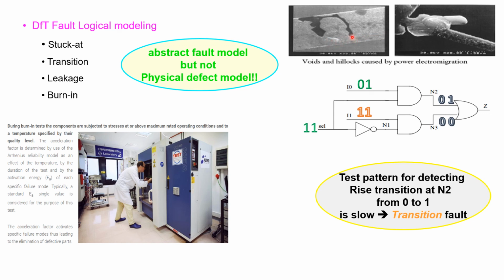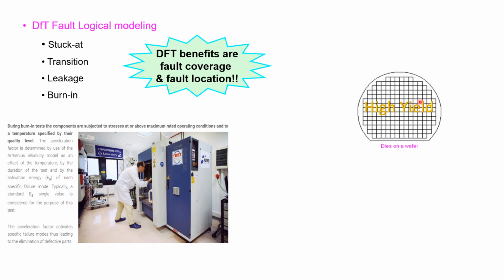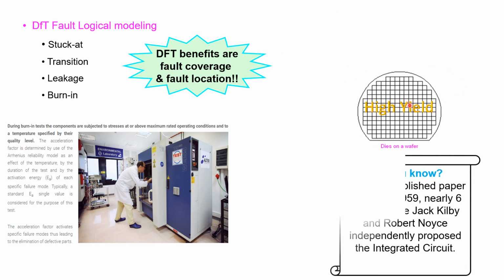Okay, a small width, I mean. So because of this, resistance has increased. Because of that, the rise transition will change, so the rise delay will also change. That should not happen. That we have to figure out in the silicon chip, and then we have to take out those offending chips. That is how we will improve the yield of the wafer.